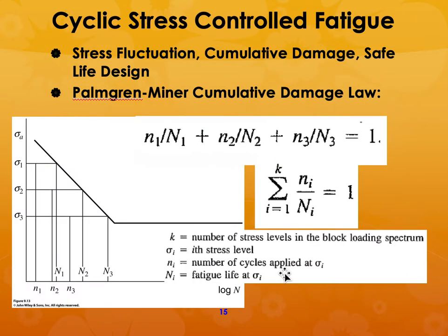Now, there is also something else. Suppose you apply different stress levels and you want to calculate the total lifetime. You applied a stress and had so many cycles at that stress level. Then you change the stress and apply so many cycles. So you want to calculate the total lifetime.